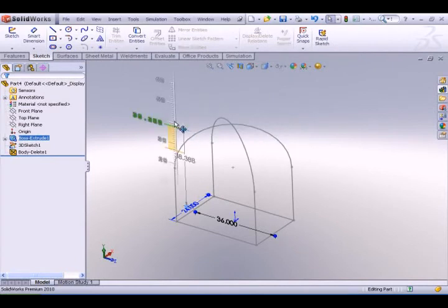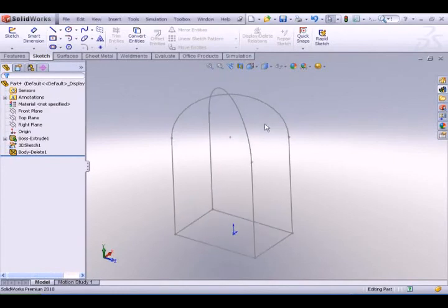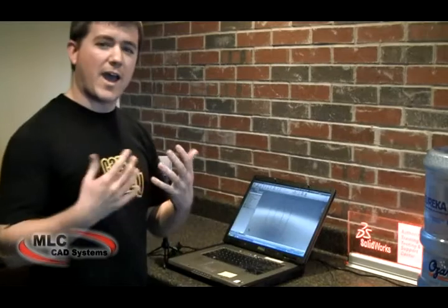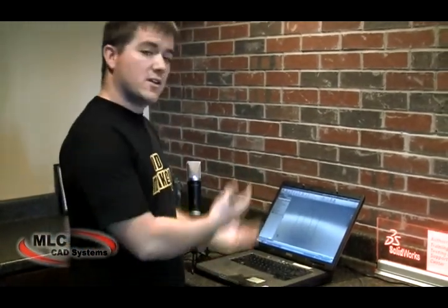And they also are going to be more along the lines of what you're used to working with, which is solid geometry. So if you're having trouble working with 3D sketches, if you're having problems getting everything to work, and you're having trouble with things over-defining, which is kind of a problem sometimes in 3D sketches, using a solid sort of as a dummy and then deleting it is a really nice workflow in order to get your geometry very quickly, very easily, but also be able to modify and work with it.